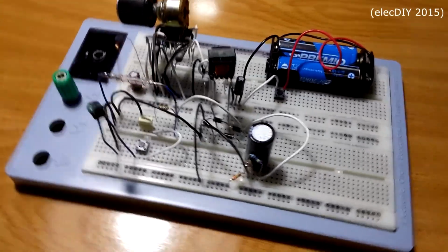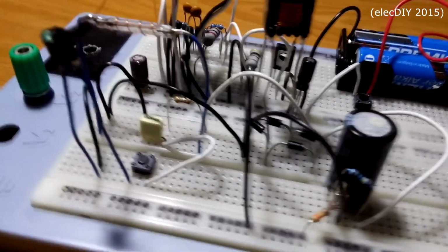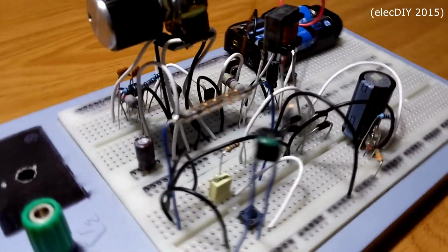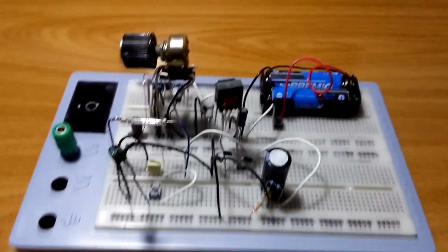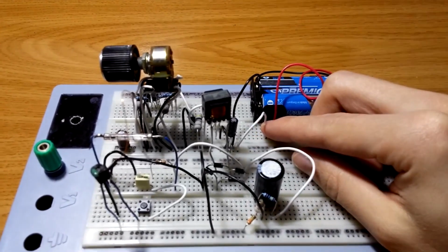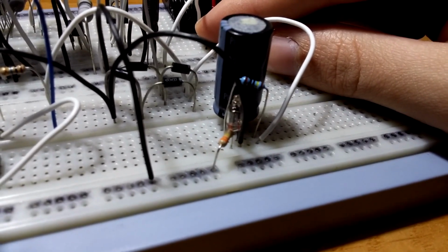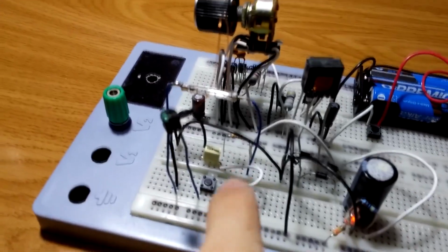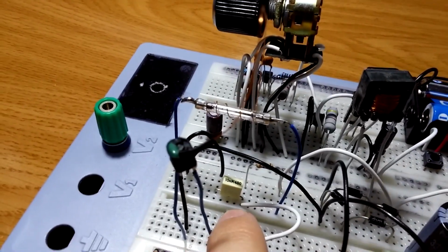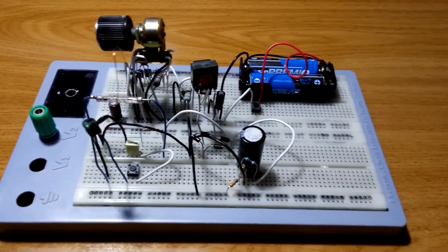Another example of an application of the capacitor is in flash photography. Even a large capacitor stores only a small amount of energy, but it can release this energy very rapidly, as for example in a flash gun. The charged capacitor in the flash gun, for example, discharges and releases around 1 joule of energy in about 1 millisecond. So this is a power output of about 1 kilowatt. Therefore, the small camera battery cannot produce this power output. That is why it takes about 10 seconds for the battery to recharge the capacitor between photographs.